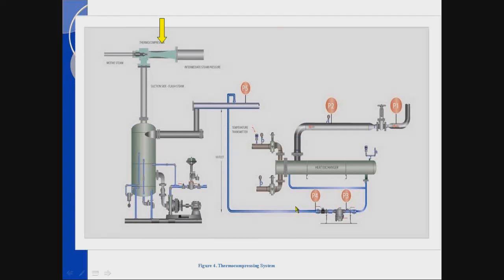Example is in this print here. If we go back to the heat exchanger that I talked about previously that does not modulate, steam's coming in at P1, across the valve, P2, we have no modulation, and we come down to P3 and P4, differential across the steam trap. Elevate the condensate up to P5, condensate is returned back to this tank that's operating at a lower pressure, somewhere below P1, so I have differential at P3 and P4.